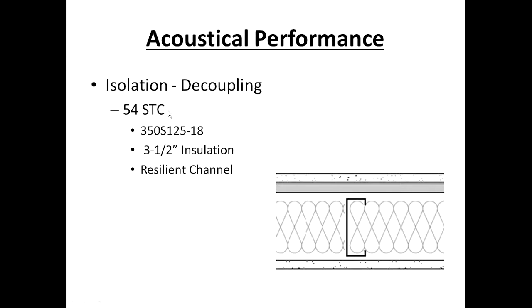Interesting thing here, when resilient channels first came out, they were designed for wood frame construction. And I had the blessing to know the guy that developed the RC1 channel, and a great guy. But anyway, we never wanted them used with steel studs, and we were adamant about it. You cannot use resilient channels on steel studs. And it was our contractor partners that proved us wrong. They kept saying, yeah, you can do it. Our concern was rattling. We thought steel-to-steel contact would not be good. We were proved wrong, which really points to the partnership that we have with everybody in the construction industry.